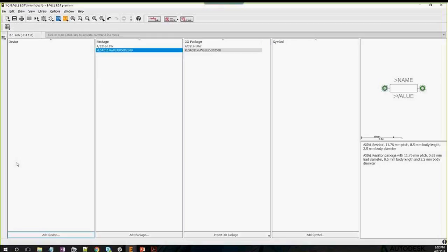My preferred way is actually having the library open side by side with the Eagle control panel, and then just drag and drop parts that I want from one library into the library that I currently have open. That works as well. It requires that the library be visible on the control panel. But if that's your use case, that's easier also. Yeah, it's a bit more visual, so it lets me navigate all the libraries. That way I could base my custom library off of different libraries as well.